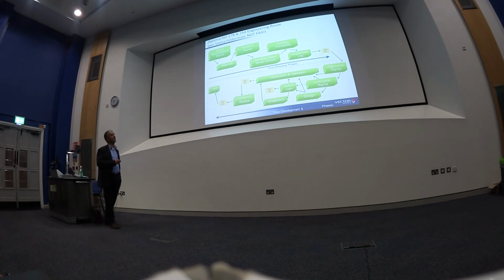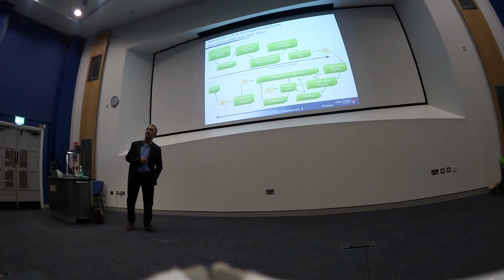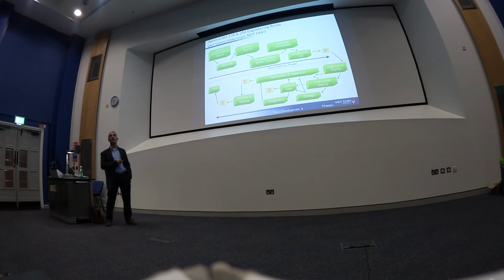And configuration management. And then you have the first SOI, stage of involvement. So here you meet the certification authority. You present your plan, your standard, your checklist, your quality assurance, etc. to the certification authority. And this is the first gate. Is it pass or not? If you pass, then you can continue the normal development activities. If you don't pass, in this case, you should go back, rework, and spend a lot of time, a lot of money to be compliant.